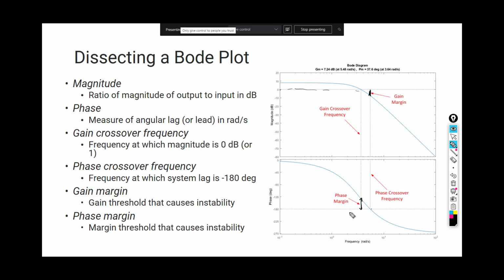So those are the characteristics. You should be able to find them, as you're able to find the settling time, peak time, overshoot, and so on. This is the same. These four points are very important: the frequencies, and just like overshoot if you wish, phase margin and gain margin, like you see here. Those are very important criteria. One, two, three, four. So you need to be able to find them if I give you a Bode plot.